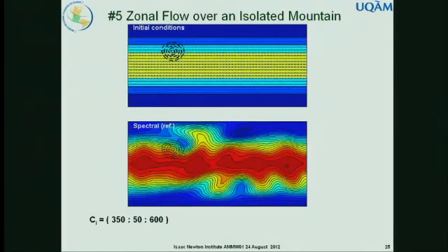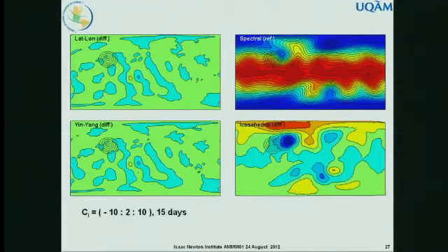I'll show here two of the cases taken from the Williamson suite of test cases. Here's the mountain, and here's the spectral reference solution after 15 days. Here I show just the difference between the spectral reference solution and the lat-long grid that ran at lower resolution. But it was run with the specification of the Williamson case. And there's the yin-yang. As you can see, the differences are very similar.